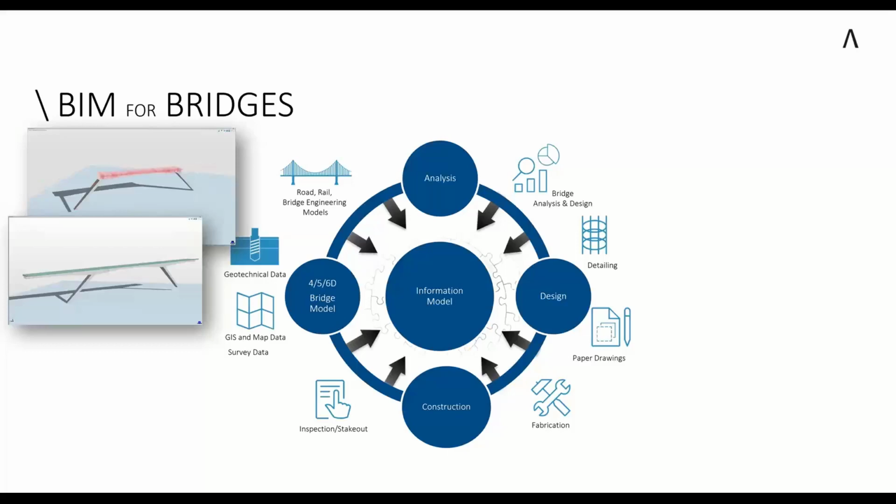This has two aspects. On the one hand, we can use this for the drafting. If you also want to have drawings of your construction sequences, you also get this split system in Allplan to make drawings from it. On the other side, it's already a preparation for the next step, which is our static analysis. When we're doing bridge analysis, it's important to consider the construction sequence and the construction stages. Therefore, this is a preparation for the analysis.